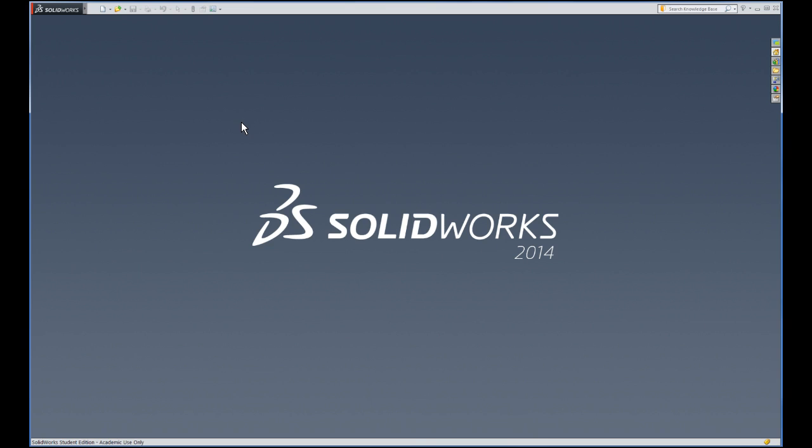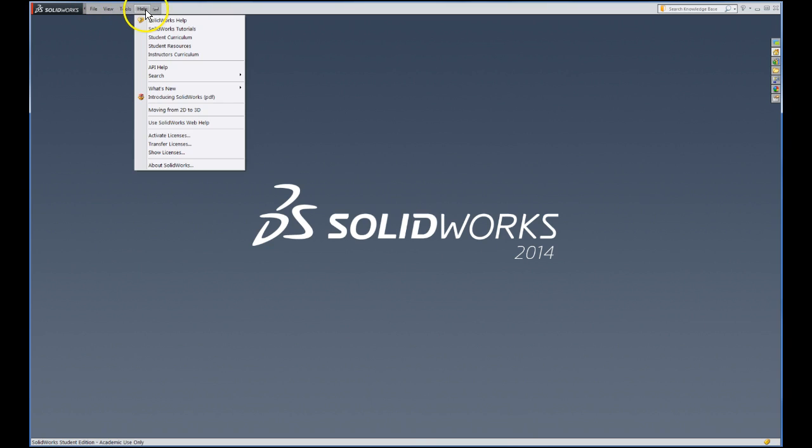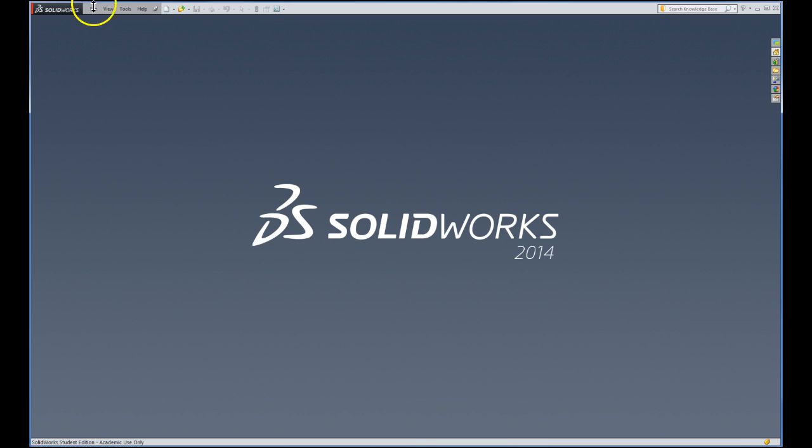There's a few things we can do to configure it. So if I move my mouse next to the SolidWorks name, you'll see 4 more drop-down menus will fly out. And these are often helpful to keep out. So if you click on the little pin next to the Help icon or the Help menu, then those menus will now stay out along with the new and open menus, etc.